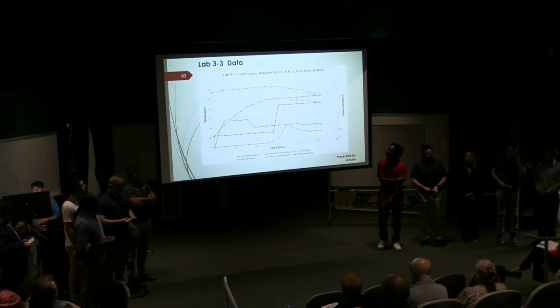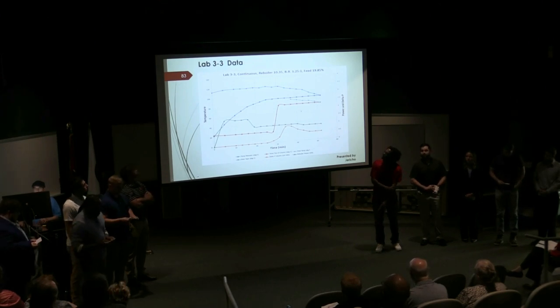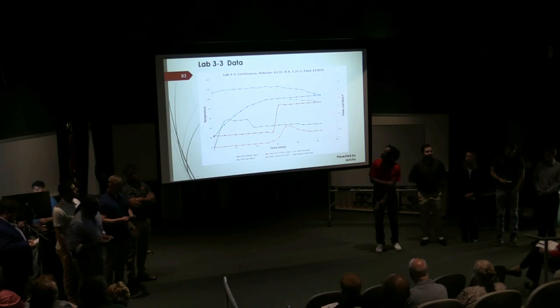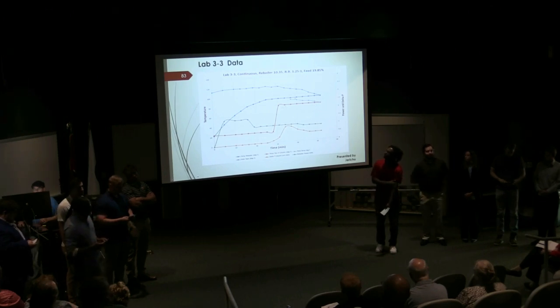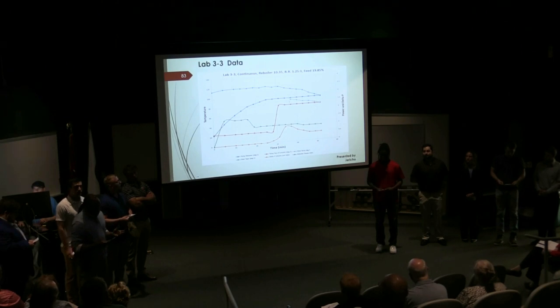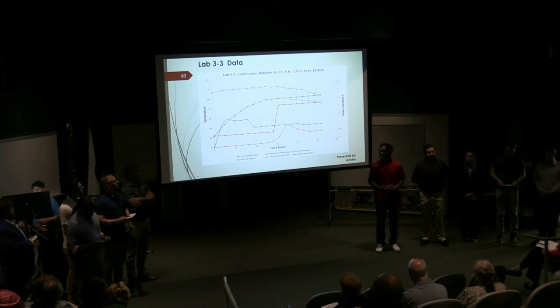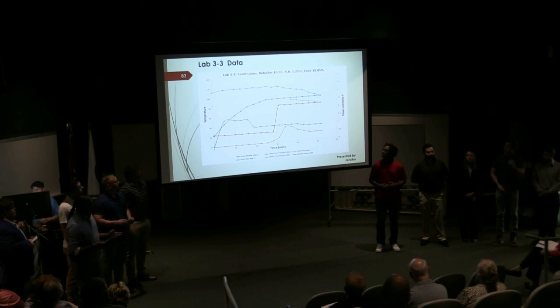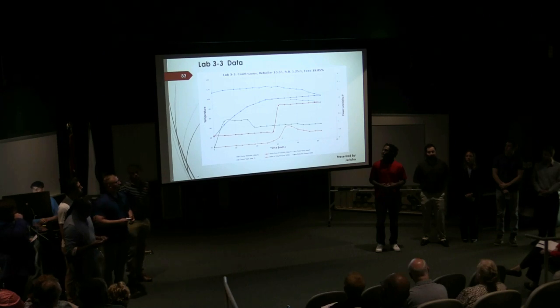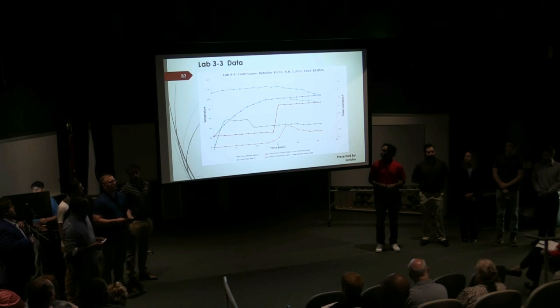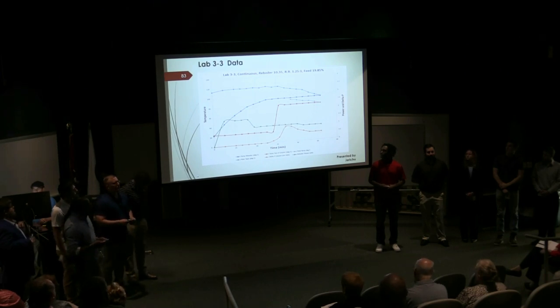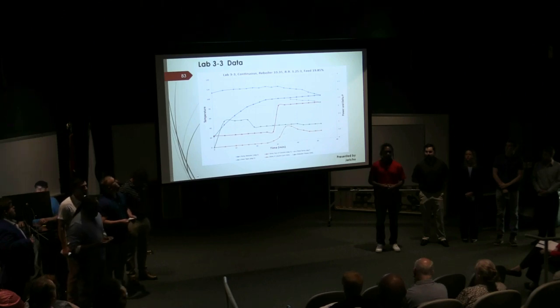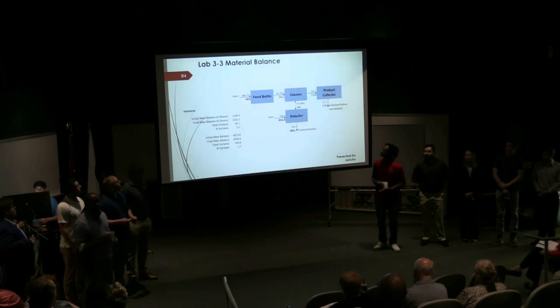In our final experiment, we ran at 50% heat tape power. The run was stable. However, we noticed the feed was both liquid and vapor going into our column. The feed temperature was above the temperature at the top of our column. We only adjusted the reboiler one time, as we did with the first 2 experiments. The pressure drop was higher at the beginning of the product collection due to higher feed temperatures at this time. But our material balance is within the desired range of variances for this experiment.